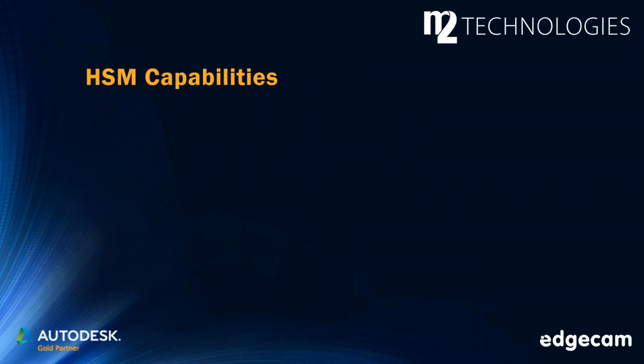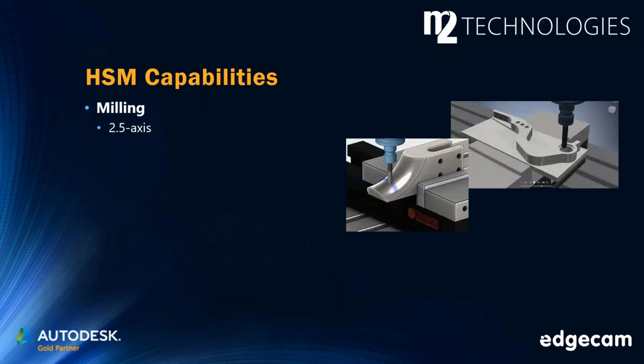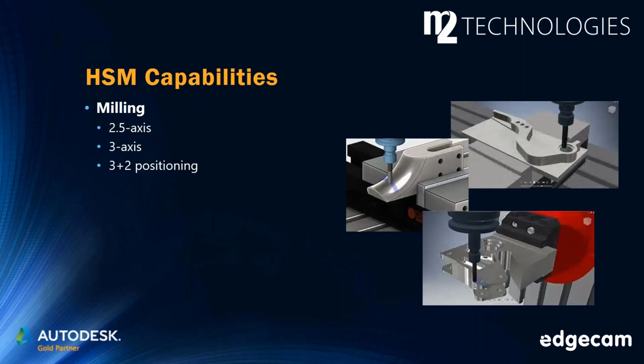Let's have a quick look at the HSM capabilities. Autodesk HSM package is able to do a wide range of milling work. That runs from your typical 2.5 axis prismatic type applications to 3D applications such as 3D contour milling. 3+2 positioning refers to a machine tool with 4th and 5th axis indexing capability, so it can do the 2.5 axis or 3 axis work from different directions. 4 and 5 axis simultaneous machining capabilities are also available, as well as inclusion of touch probes such as a Renishaw probe on the CNC machine.